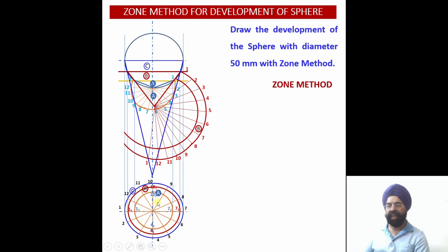And this is the reason I did not draw the top view closer to the front view. Had I drawn the top view closer to the front view, this would have protruded into this particular zone. Once it intrudes into this, the clarity would have diminished. Now you see once again, O1 corresponding to the blue circle. I started with green over here, I moved on to red over here, and I have moved on to blue color, the outermost circle, corresponding to the diameter of the circle.